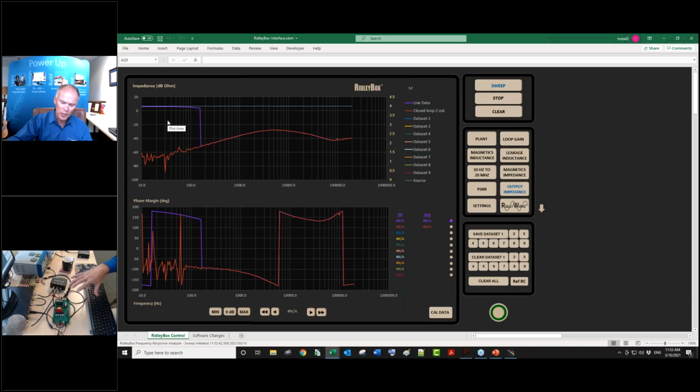If I measured it open loop, I'd kind of get the LC filter characteristics, but not really, because the diode would be involved, because it doesn't want to go backwards. So you have to apply power to it to look at the output impedance. There's nothing useful you can do with just a dead circuit in measuring. When you're in voltage mode control, you could do something there, but when it starts to switch, it's different.